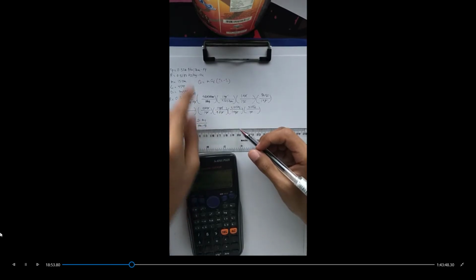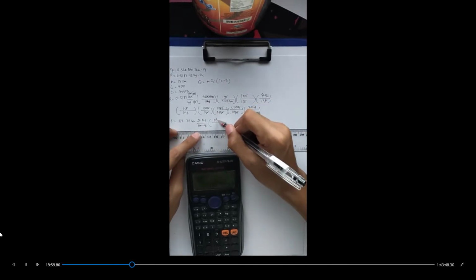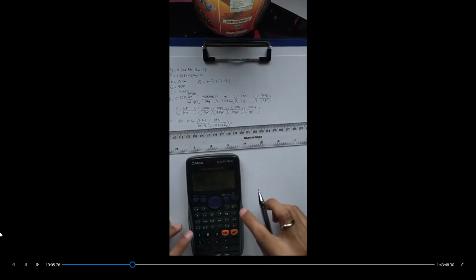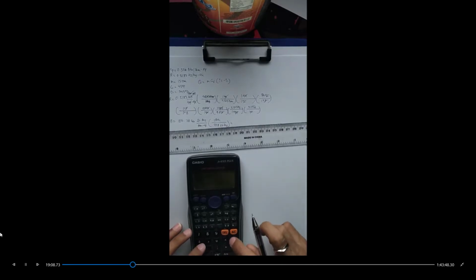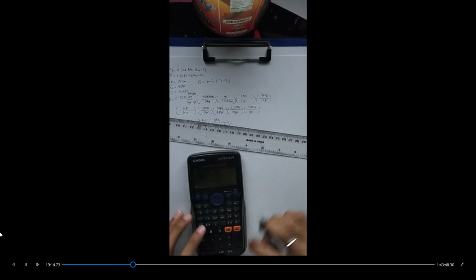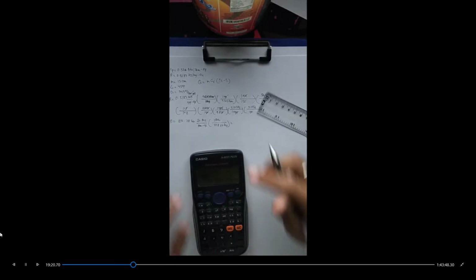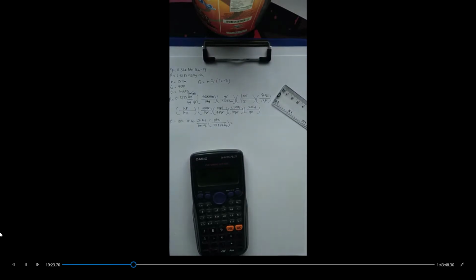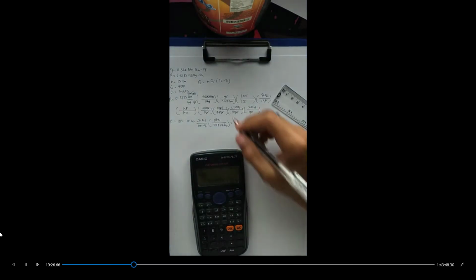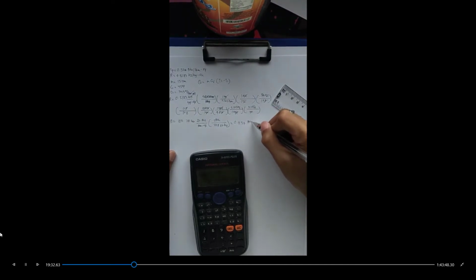In order to convert foot-pound force to BTU, we are going to multiply this equation by 1 BTU here at top and then 778 foot-pound force at the bottom, like that. And we can now have the final value of our R in English system, 103.7866 divided by 778. So by 778, and the answer would be 0.1237 BTU per pound mass degree Rankine. Alright.